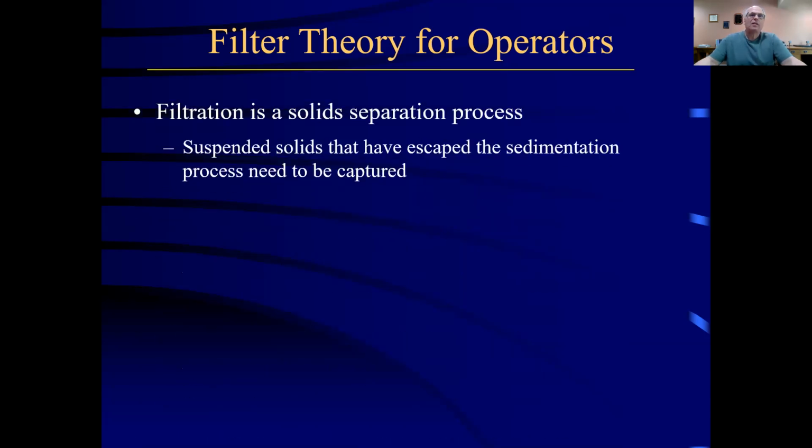So let's think in terms of filtration being a solid separation process. In other words, we have contaminants that are suspended, not dissolved, but suspended in the water that we're treating. And some of those suspended solids that escape the sedimentation process and go over to our filters need to be captured.